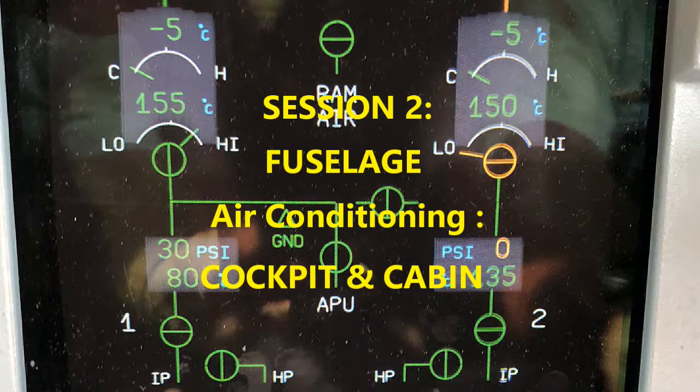You've got some that are installed along under the cabin floor, left and right. You also have smaller diameter riser ducts, which are connected to the main ducts. Those supply air through the outlets that are installed below and above the overhead bins. So that's where those are located. You've got some more riser ducts at the rear of the forward passenger doors, and also aft.